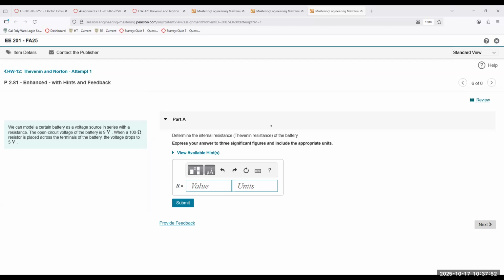So you have a large circuit, there are multiple voltage sources and current sources present in the circuit, and there are several hundred or thousands of resistors present in the circuit. And what his theory said was you could take all of the sources in that circuit and represent them as one single voltage source. And you could take all of the resistors in that circuit and represent them as one single resistance. And the resistance and the voltage source would be in series.